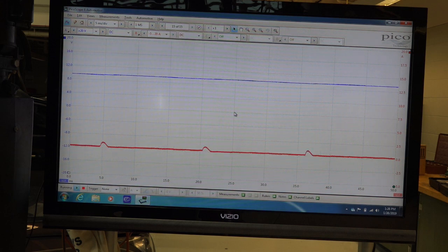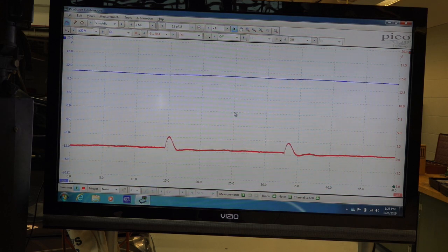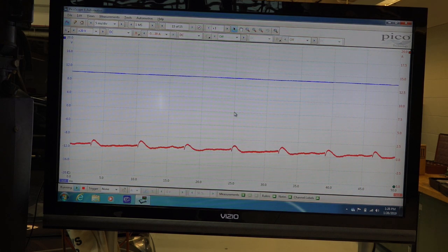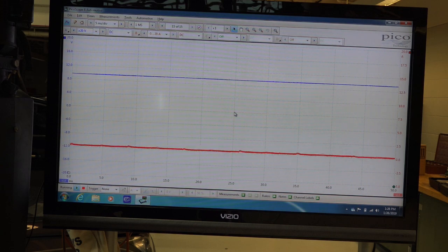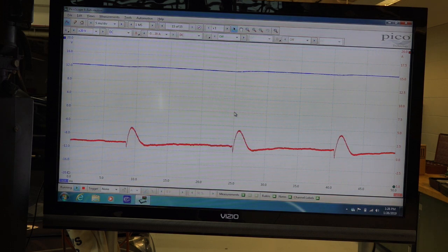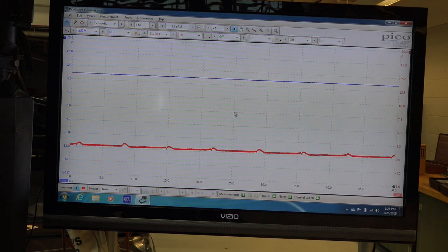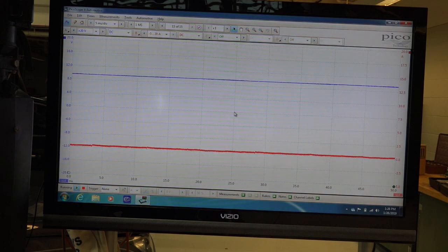All right, scope's now connected. The top or the blue line is the voltage at the speed control of the blower motor. And the red trace, or the bottom line there, is the current there at the battery. Next thing, I need, again, to try to determine whether or not that voltage on the blower speed control is coming from the programmer or not.